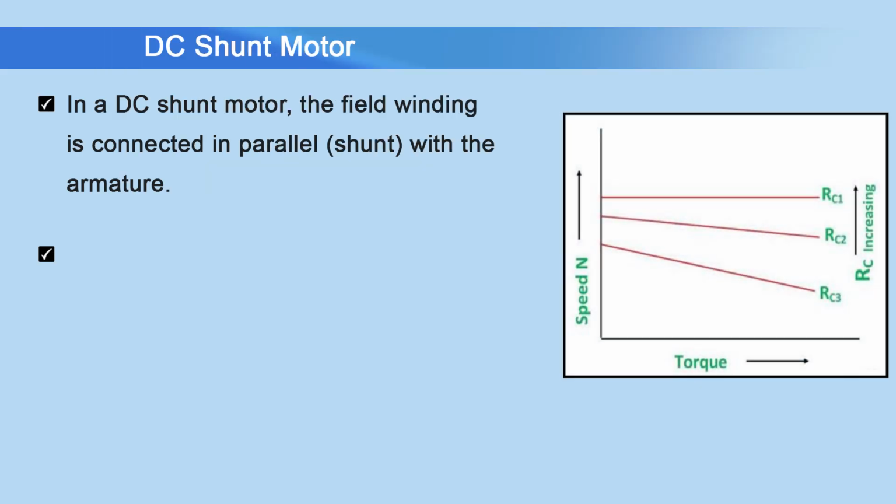The torque speed characteristic of DC motor is very important to understand for controlling and designing of a system that uses these motors. Okay, so we will see the DC shunt motor and its different application. Let us understand the speed torque characteristic of DC shunt motor. In a DC shunt motor, the speed remains relatively constant with varying torque or load, we can say. Okay, so it means the speed is almost constant with respect to the change in load.